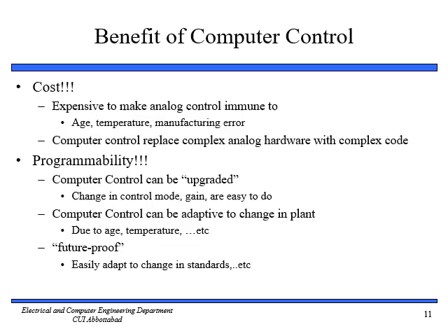Let's move on to the next slide. In this slide we will talk about the benefits of the control system. Control systems can be implemented by continuous time or digital approaches. Since most processes we are interested in controlling evolve as continuous variables in continuous time, computer-based control approaches add complications such as quantization, overflow, aliasing, and computational delay. It is important to consider briefly the benefits obtained through embedded system control. So what benefits can we get from computer control? Number one is cost, and number two is programmability.